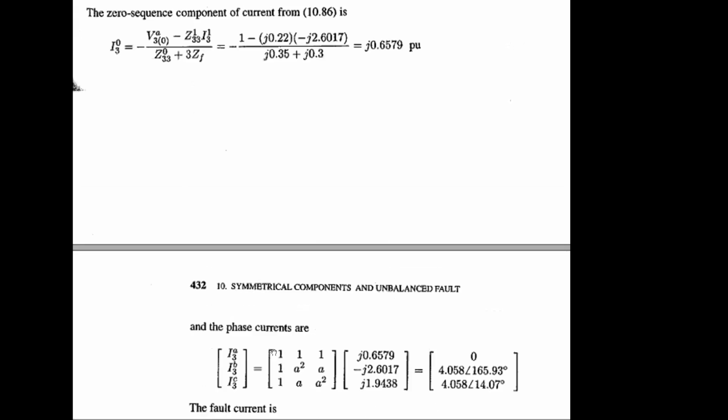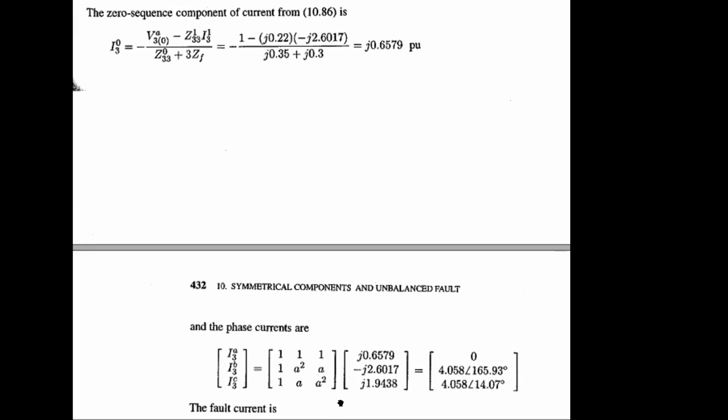For double line to ground fault, you have to make an addition after the calculation. That means when you complete that calculation, you have to use these two pieces of information to get the final fault current, which is only for double line to ground fault. Okay, remember that for double line to ground fault, after the solution, you have to use the final outcome. This one.